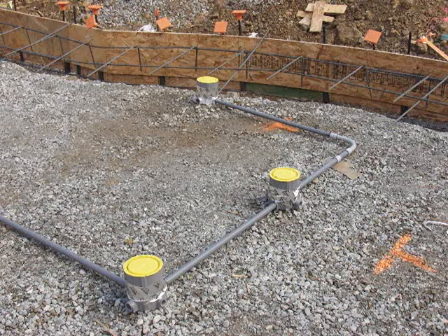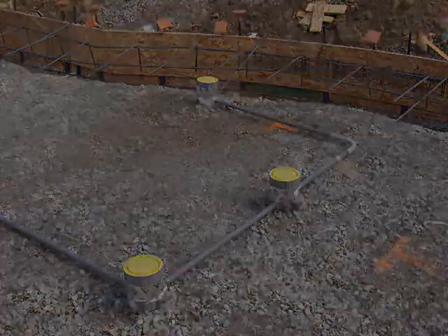So the electricians would actually prefer you leave it high. They can then come back with a Sawzall and cut it flush with the concrete. It's a little bit backwards than what might be intuitive, but that's the way that the electricians ask for it to happen. So basically set them. You can put little pieces of rebar down into the grade that'll hold them at the right elevation and in place. And as you're doing your pour, you just want to make sure that they stay above the finished level of the concrete.